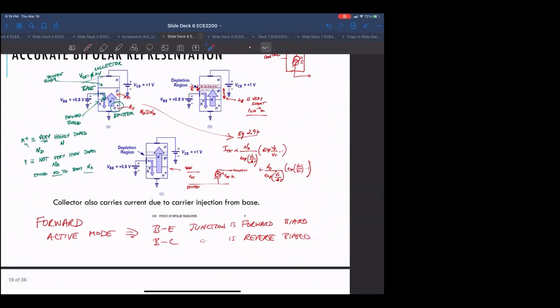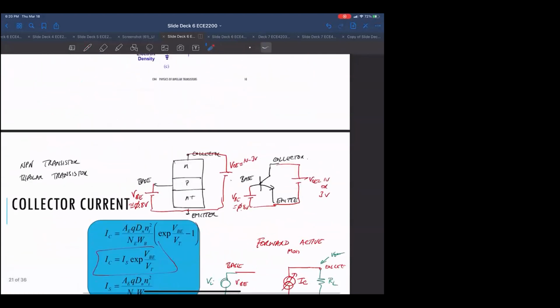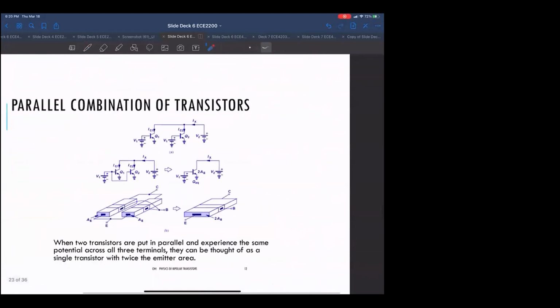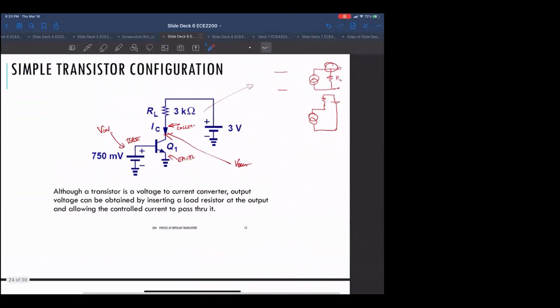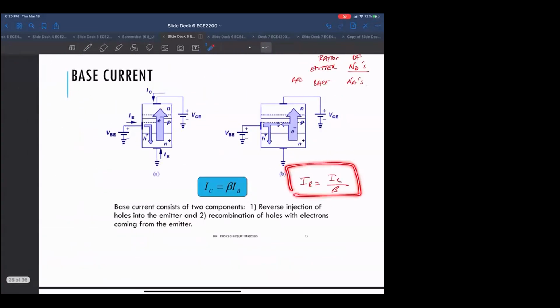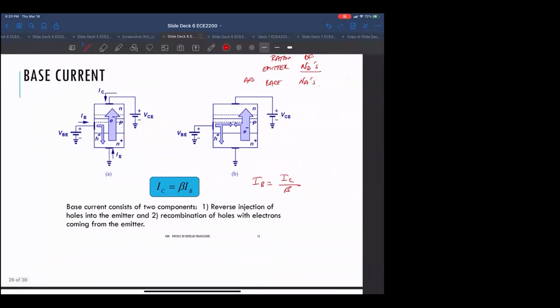Yeah. So remember I wrote this equation from chapter 2, and there's basically almost all of this. This is the emitter current, essentially. It has to do with the doping concentration of the emitter, and this is the base current. Okay, and basically this ratio between this and this decides what's the ratio between the emitter and the base current. And since most of the emitter current becomes the collector current, I can just say that it's the collector current.